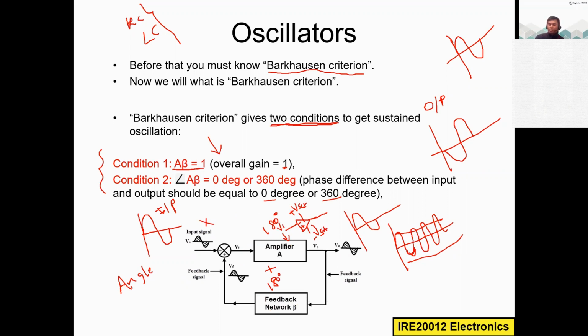This is just the biasing voltages. So whenever this amplifier is powered up, thermal noise is naturally generated by these devices. Because of this closed loop amplification, this thermal noise gets more and more amplified, and it will give enough oscillations at the output.